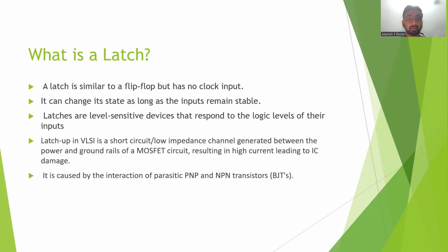Next, we'll know about what is a latch. A latch is similar to a flip-flop but has no clock input. It can change its state as long as the inputs remain stable. Latches are level-sensitive devices that respond to the logic level of their inputs. Latch-up in VLSI is a short circuit or low impedance channel generated between the power and ground rails of the MOSFET circuit, resulting in current leading to IC damage. It is caused by the interaction of parasitic PNP and NPN transistors.